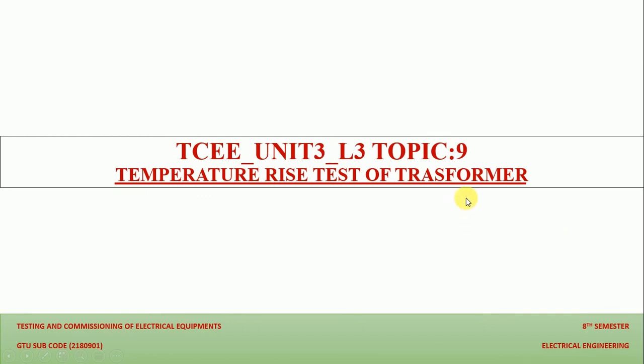Now let us discuss topic number 9, that is the temperature rise test of the transformer. This test is again important for the long life of the transformer, because as we use a transformer for a particular purpose, the transformer gets loaded, so a heavy current will flow through the transformer windings.